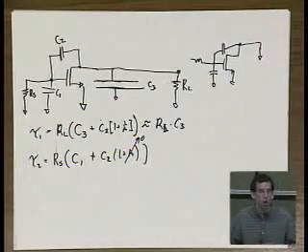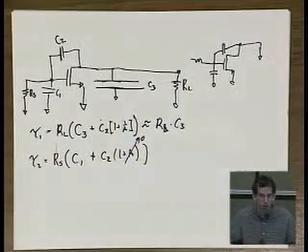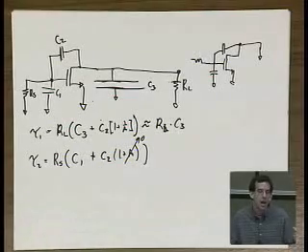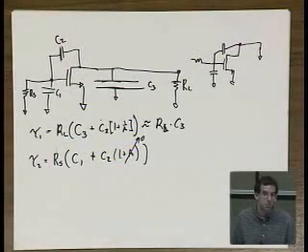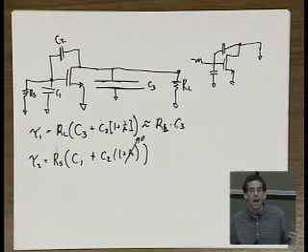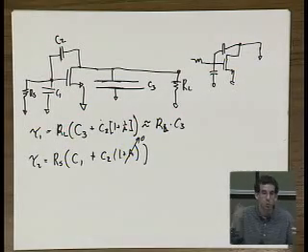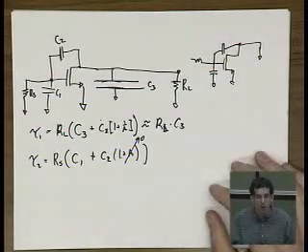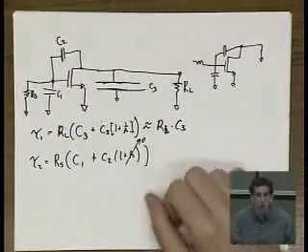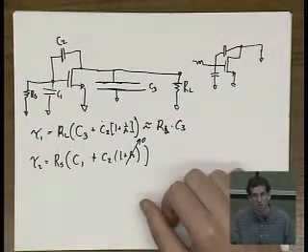And then if all those individual time constants are still at approximate levels, then the analysis can be really useful. If you find that one of these time constants is way bigger, in other words, the pole associated with a capacitor is way smaller, then you know you're onto something, and you can move forward by making some of these approximations.